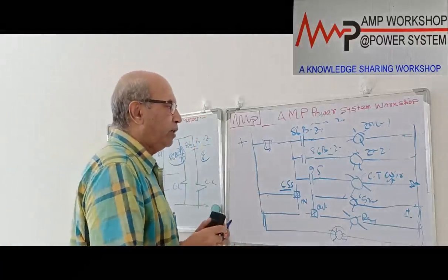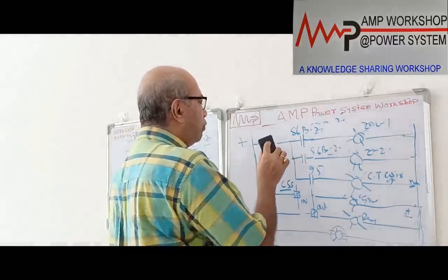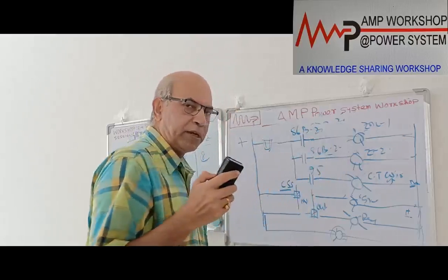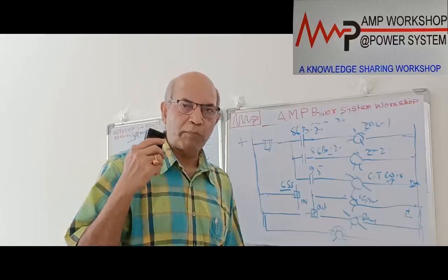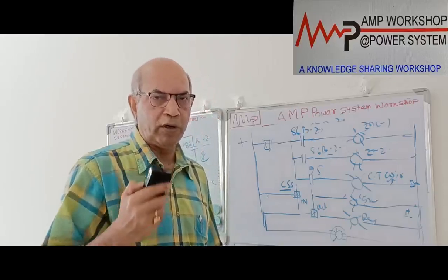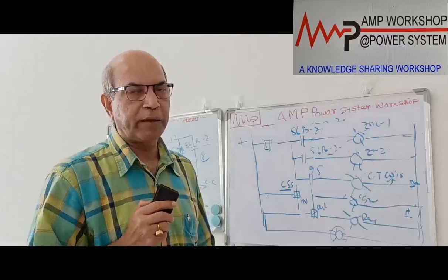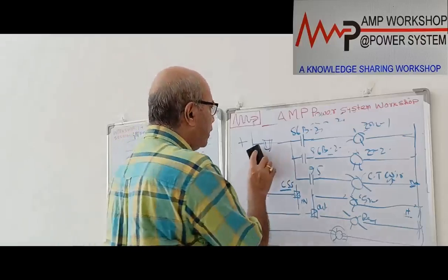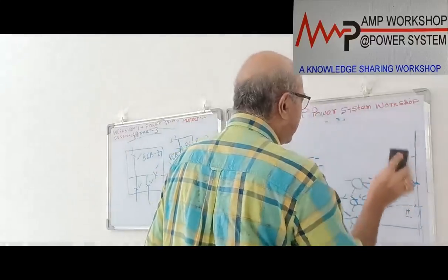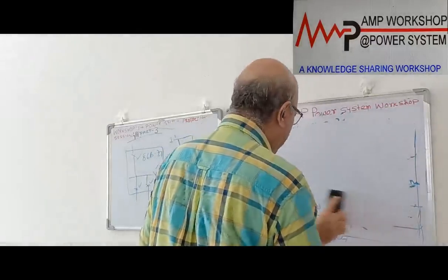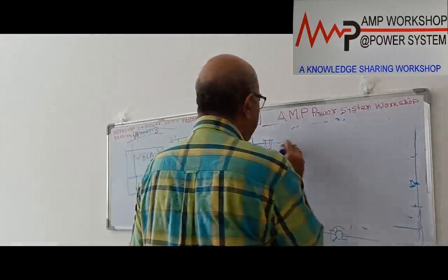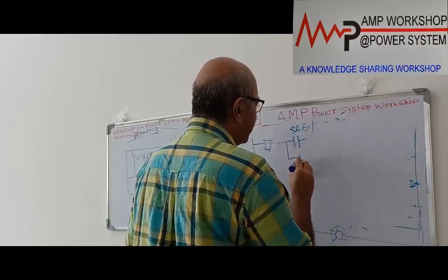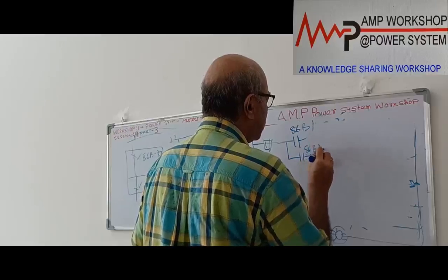Okay. In addition to this, for busbar protection zone 1, zone 2, we take an alarm also. It is not only the indication. When the busbar protection operates, as I said already, the total process plant will be shut down. In the case of a busbar fault, all the feeders on that bus section will be off, so a huge process plant will be off. So it needs a siren. How do they do it? In addition to this indication, they put another relay, a supervision relay. Suppose this is 86B1, okay, and then it is your 86B2, okay.